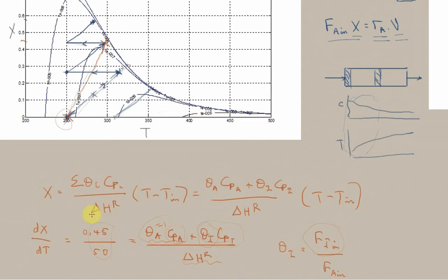And so I'm claiming now that we have fixed the inlet flow ratios and so on. And of course, the heat of reaction is fixed, so the gradient is the only thing that's fixed. And so we are now free to choose an inlet temperature, and we are free to choose where to stop along the lines and so on.